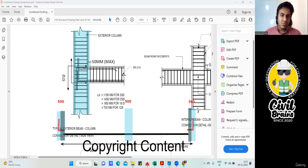This part, whatever you have, this is your development length. How much is it? They have shown here 57 times the diameter of the bar. Same thing on this side too, and from the bottom also. I did it for the top.